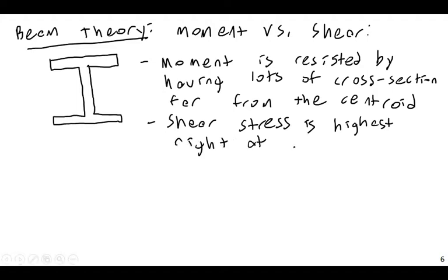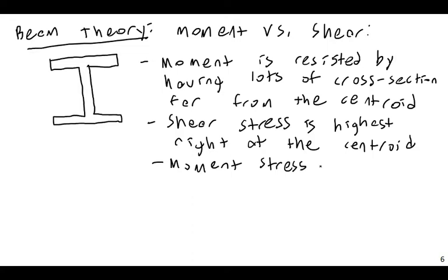More or less, there are some details of that, but generally speaking, it's highest right at the centroid. And bending stress is highest at the edges, or at the outermost fiber.